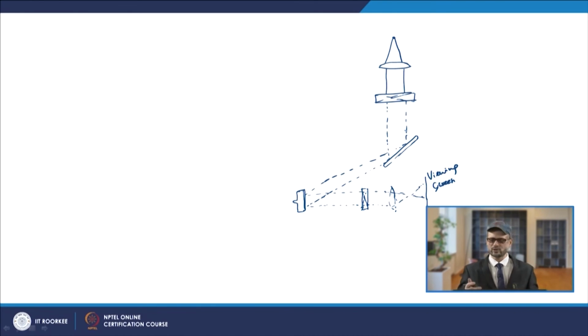So isoclinics refers to the black bands that give you the direction of the principal strains, and you have the isochromatics, the colored fringes which you obtain, and they give you the magnitude of the maximum shear strain. So you have only one reading of the fringe, with the light going under normal incidence through that photo stress coat.